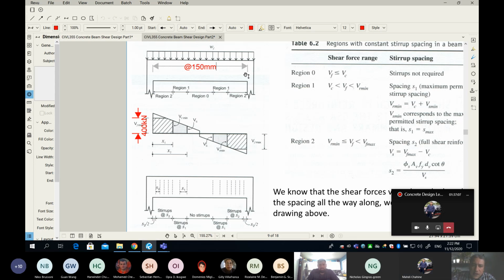Remember, look at where I placed the 400. It is at the maximum shear. And based on the remaining for the stirrups, I found 150. Okay? I'm asking you, should I take the 150 and place it everywhere on the beam between the columns? No, it'd just be a waste of material. You're going to end up in a ductile failure if you place it like that because you calculated it for max shear. That means it doesn't need it everywhere at 150 millimeters.